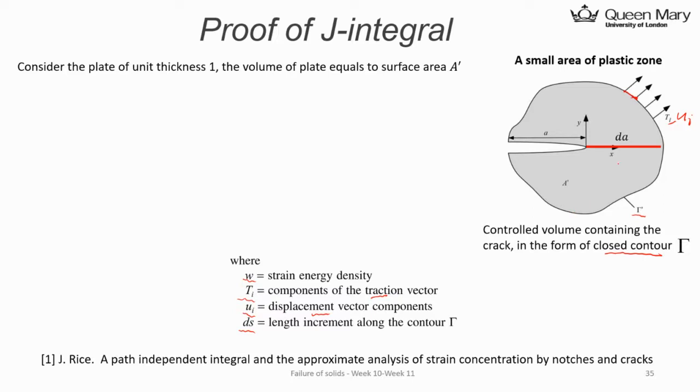I will show you. So now if you assume this small amount of material has completely fractured, so the crack will start from this point and travel and eventually fracture the sample. So now you can think about after the fracture, the total amount of strain energy will equal 0, right?